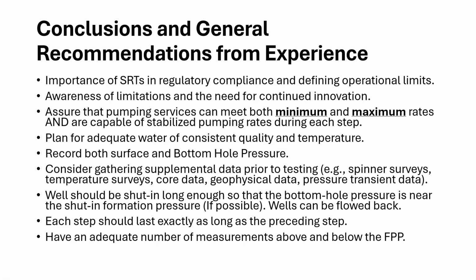So that gets us to some of my conclusions and some of my recommendations from our experience. I would just want to highlight that in regulatory compliance and defining the operational limits, maximum injection rate and maximum surface pressure, the step rate test is the go-to test for regulatory bodies. And awareness of these limitations is important when generating a thorough analysis. We can continue to innovate along those lines using more tools that are developed as we go on.